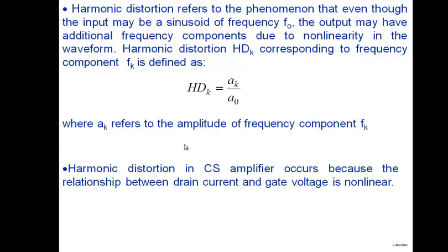Okay, and you can sum these harmonic distortions in an RMS manner, and you get total harmonic distortion. So let's calculate harmonic distortion then, because without that we cannot specify what the output voltage swing of my amplifier is. So the way I'm doing it is as follows. Note that this is the fundamental equation of a transistor biased in saturation region.